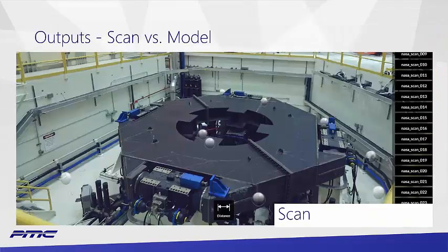So another thing for anyone who's new in scans that we run into is a lot of people see a picture like this, which is a scan, and they don't understand why it is fundamentally different than CAD. Even though this really looks great and it looks like a photograph, it's actually not. It's individual dots. Those dots can't necessarily be used to create design documents or any kind of derivative CAD work. They can be created in sort of a hybrid environment, but in general, if you're doing a lot of work, you need to convert this to CAD so you can produce clean drawings.